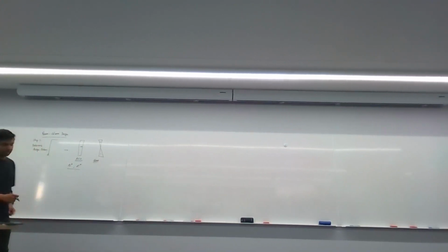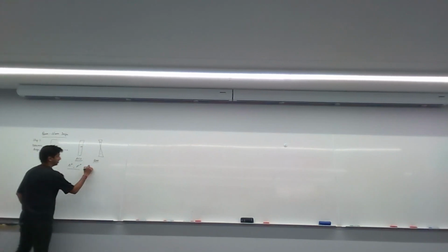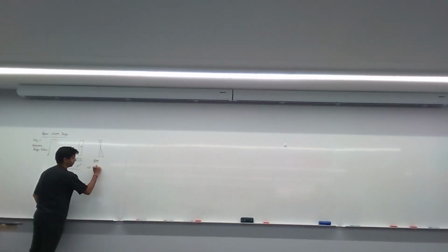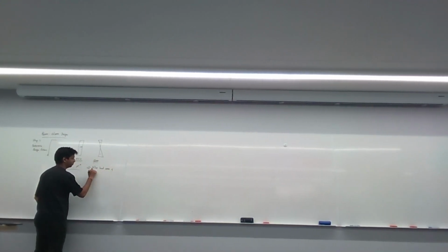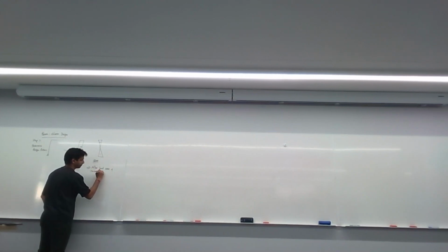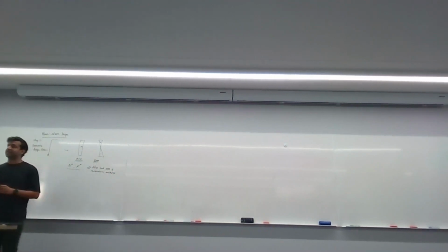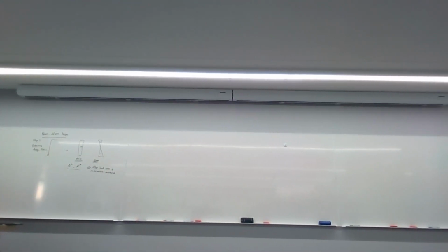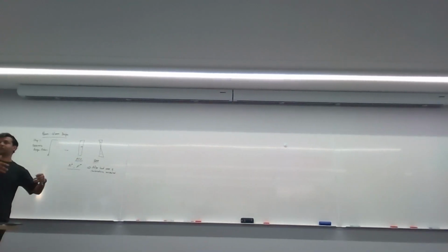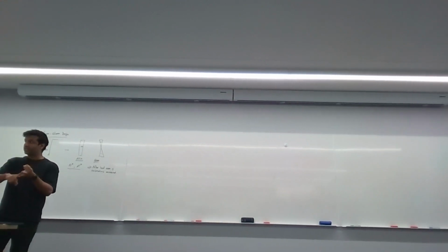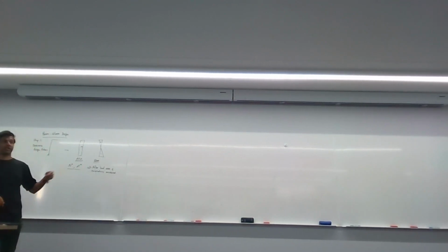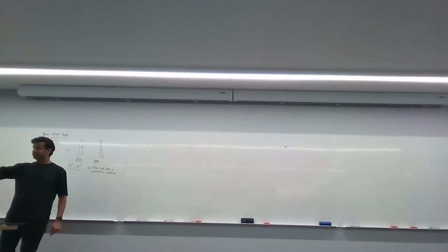Now remember, the other thing to take into account is your load combinations and load cases. When you're doing an ultimate design for a beam column situation, you're using the ultimate limit state. So you need to run through all of the different load combinations. What are some of them? 1.2G plus 1.5Q, 1.35G, and generally for a beam column question, your bending is coming from something like wind, right?